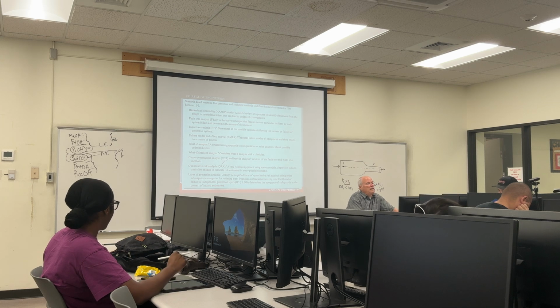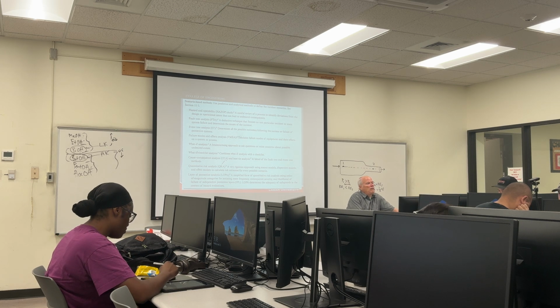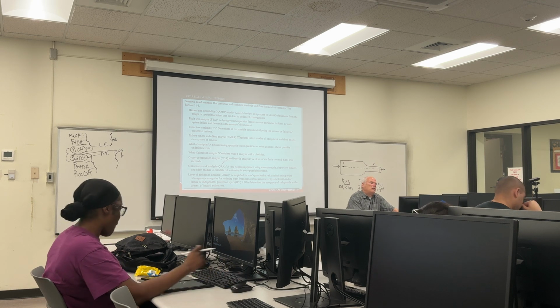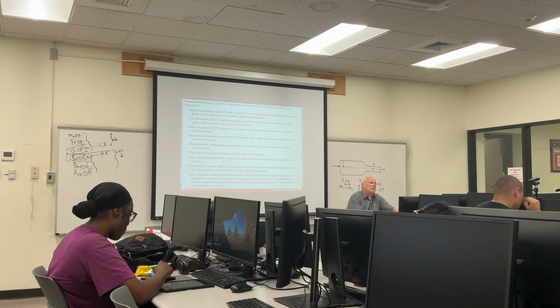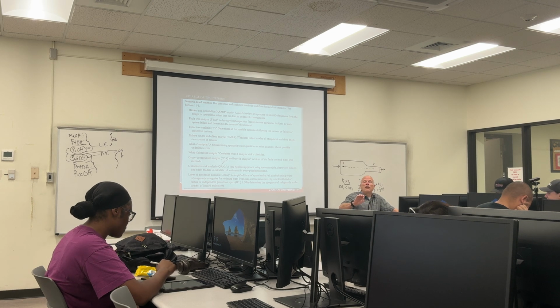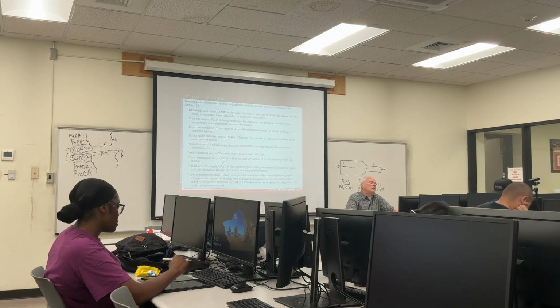And then you got scenario based methods, of which the HAZOP is one. So for the HAZOP, you go through and you systematically look at different scenarios that could occur to cause the hazardous condition.